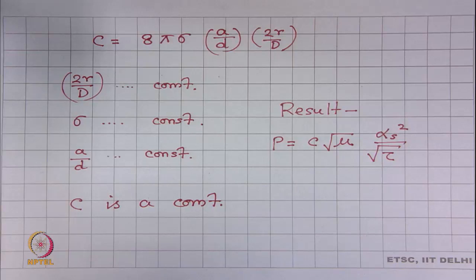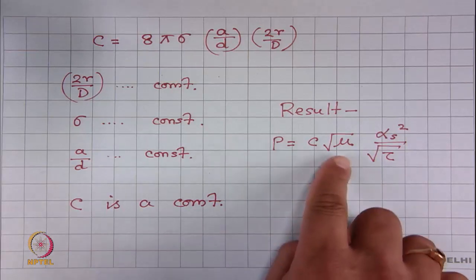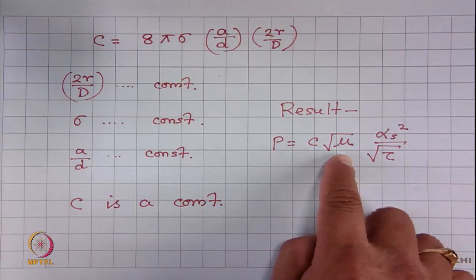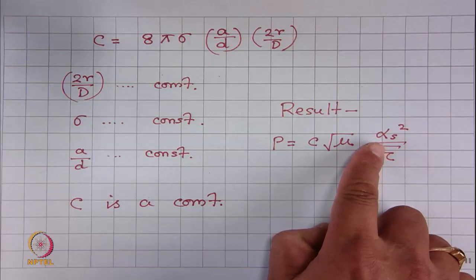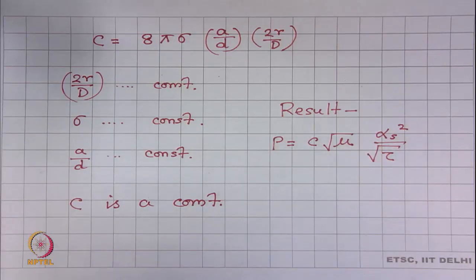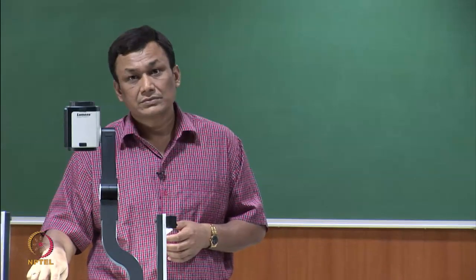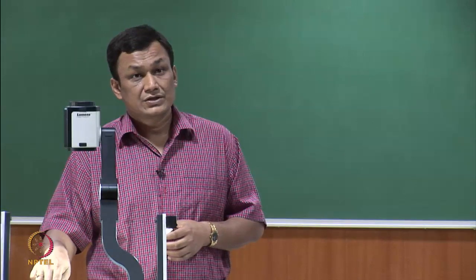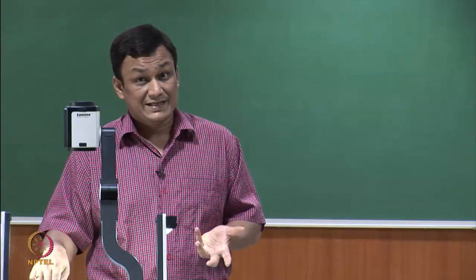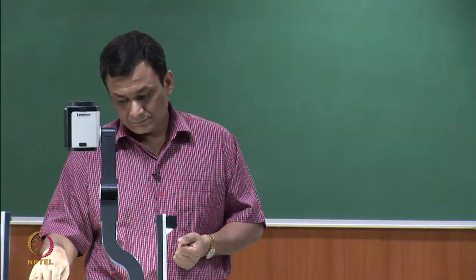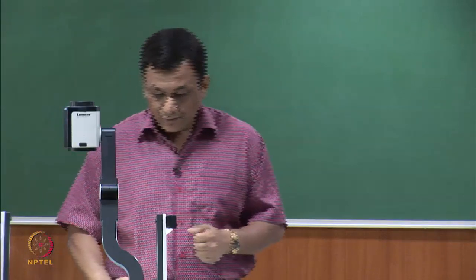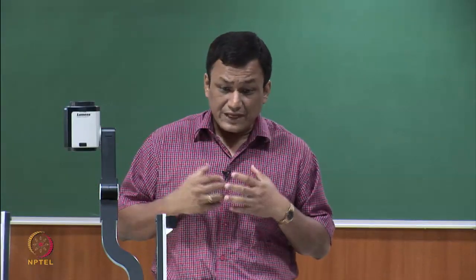So, important relation, P is the pressure in the compression zone. How much pressure is developed in the compression zone because of twist, which is related to packing density, alpha s twist coefficient or twist multiplier, right, and tau relative yarn fineness. So, yarn tex by fiber tex. Now, that means what?